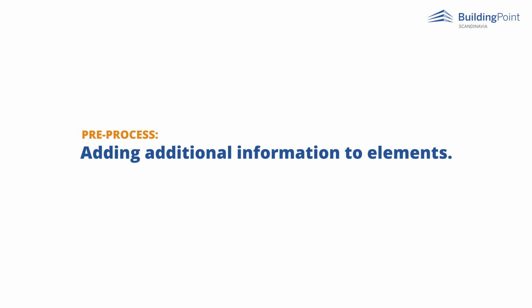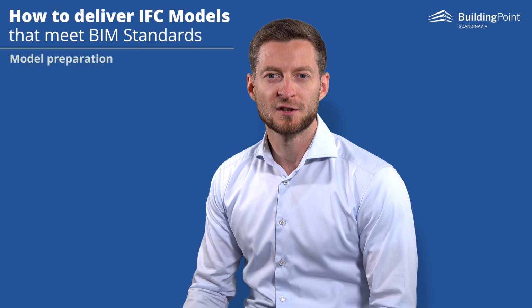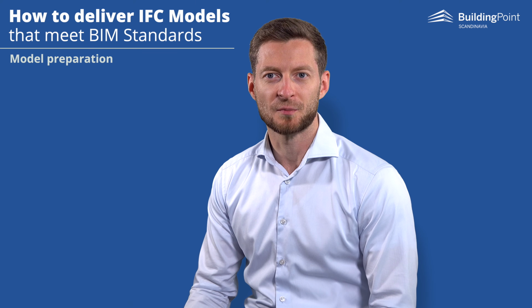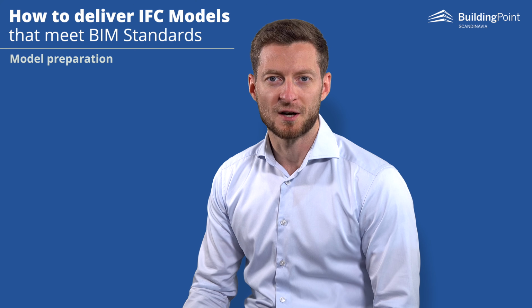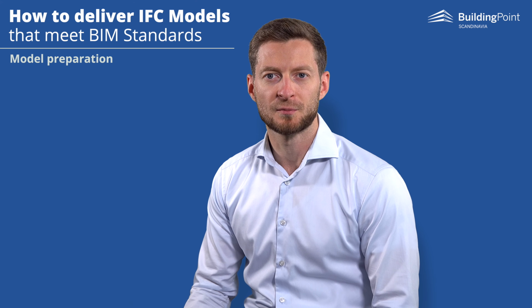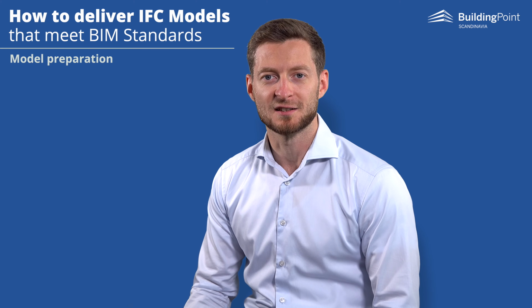After setting up the hierarchical structure in our model, the next step is to create the required additional data for our elements, commonly known as user-defined attributes, or UDAs. UDAs allow us to include custom information in our model, which is essential for meeting specific project requirements. For this demonstration, we will focus on adding Statsbygg TFM properties required at level 2 of the project, but keep in mind that this approach can be adapted to any additional information.